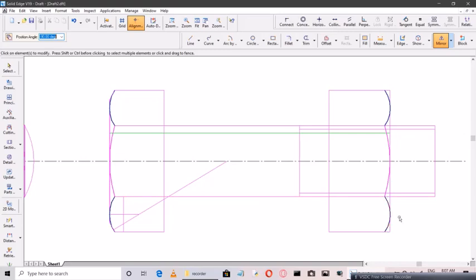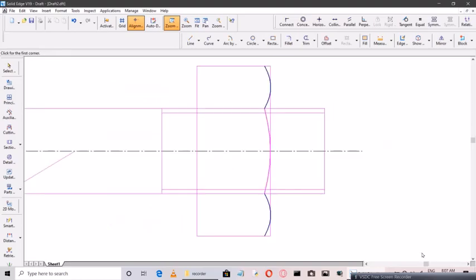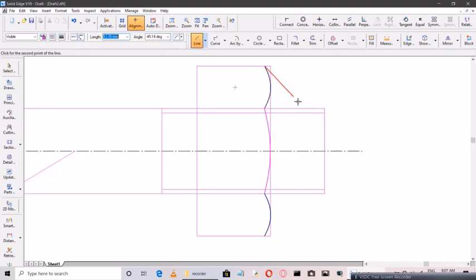Now you need to select the objects here. Use the Control key. Then the angle has to be 180 degree. Then provide a midpoint here. Then you snap exactly to the vertical position. You got it here. Now mirroring is over.